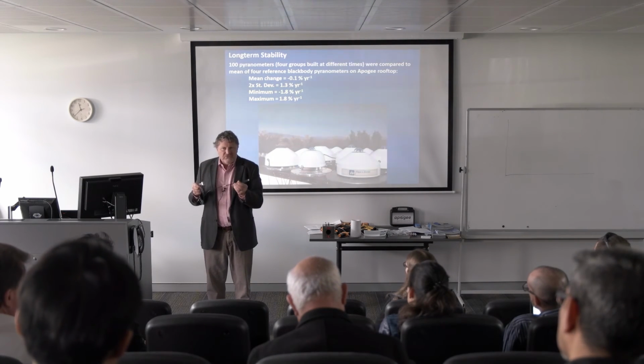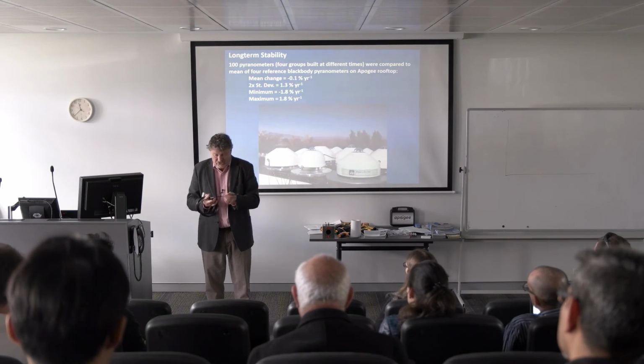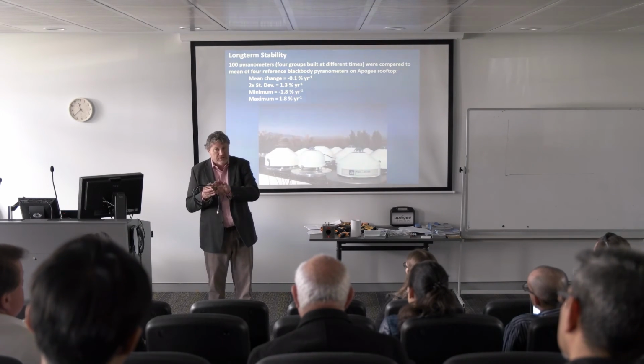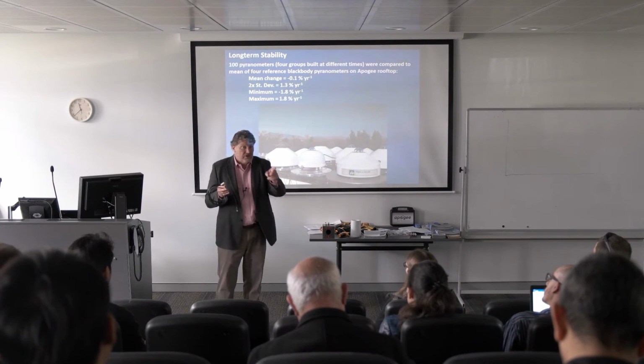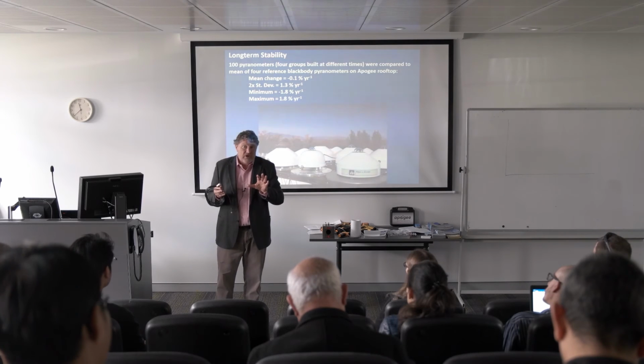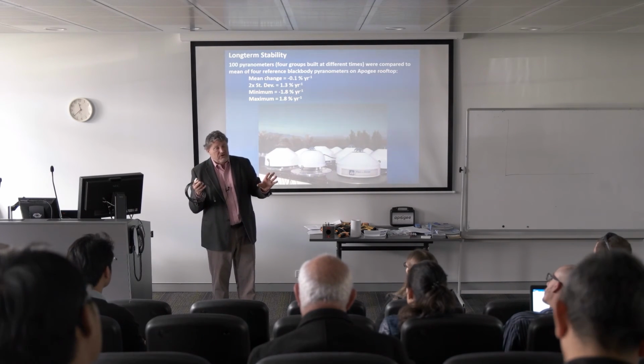The other specification that's good to look for in sensors is shielding for electromagnetic radiation, which is just wrapped with tinfoil and grounded at the other end so that you don't get electrical interference. Inside in greenhouses, this can be a particular problem if they're near fluorescent lights or equipment.